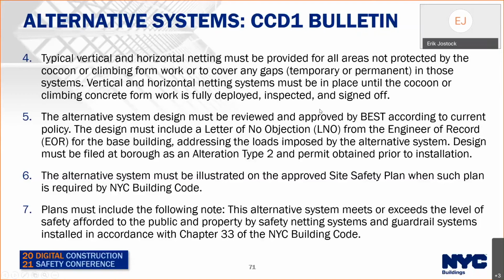And these are no longer reviewed at the borough. They're submitted via DOB Now, and I believe the hub full service team is reviewing them. But when these systems are proposed in lieu of horizontal and vertical netting, CSC is performing a secondary review of these systems. So you can still comply with the memo. You don't need to submit a CCD1, but we do need to perform a secondary or parallel review.